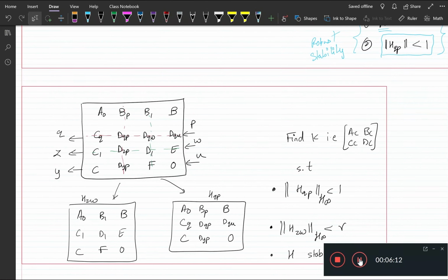So we now write the system again as we saw in the review, but now we have it in this form. If we have an integrator, we can write this as a matrix. So that's our open loop system with W, which is our disturbance here, and U as input channels, Q, which is the uncertainty channel, Z as the performance channel, and Y the control measurement.